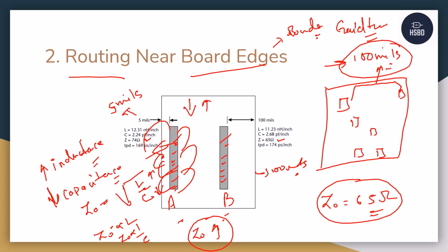In PCB designing, there is something called route keep out. The main purpose of route keep out is to keep the traces away from the boundaries also. In case of high speed board design, we never tend to put our high speed traces near the board edge at all, because impedance needs to be maintained at very high priority in high speed board designs. So this guideline explains that you need to put your high speed traces inside the board and not near the edges of the board.